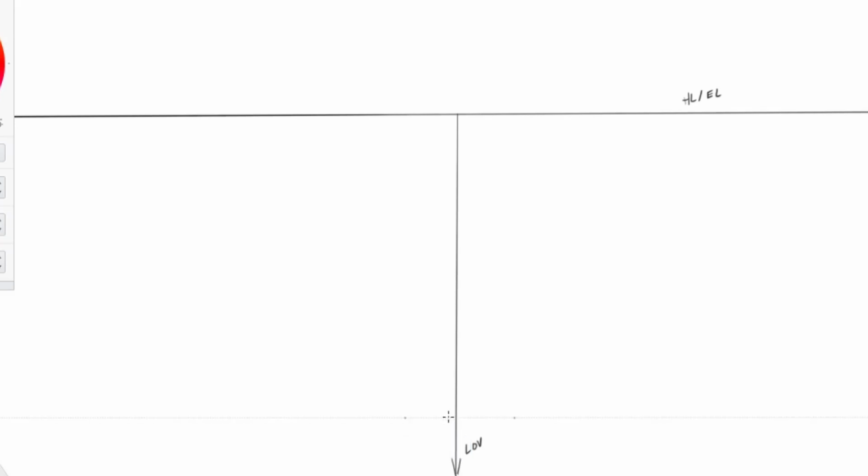I'm going to create a line right here, which is going to be for the station point, and from the station point, I've just arbitrarily selected it. I've just put it anywhere on this line. Now, from that point, when you grab your ruler, you need to find your protractor and you say, what's a 45-degree angle out from that point? I'm going to draw this in red right here. A 45-degree angle out from this point is going to be right to about there.